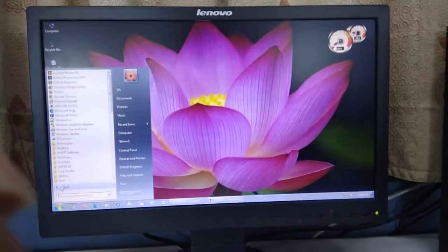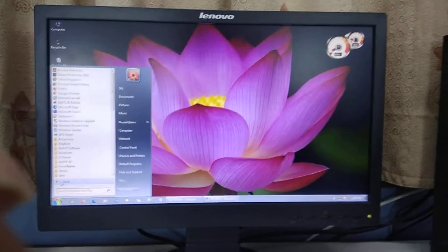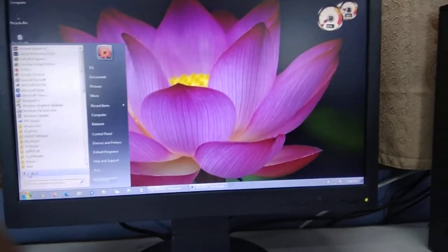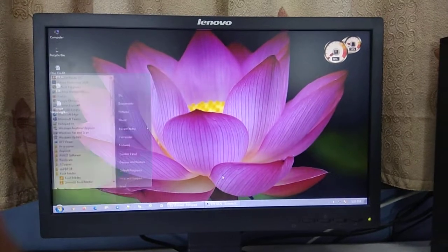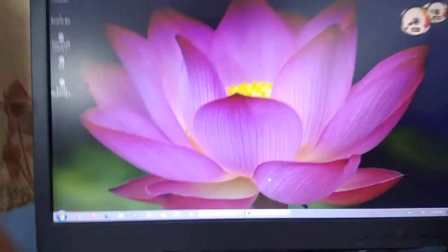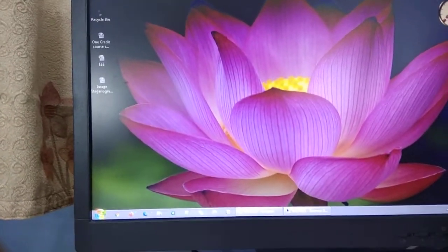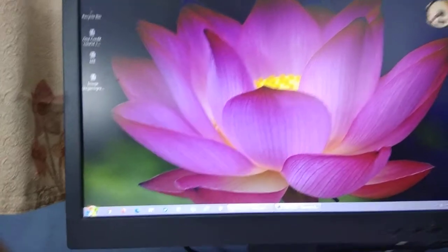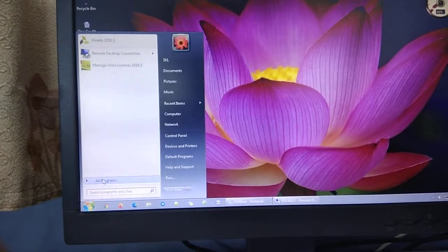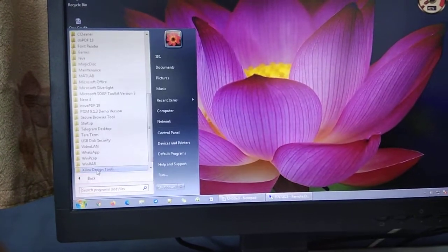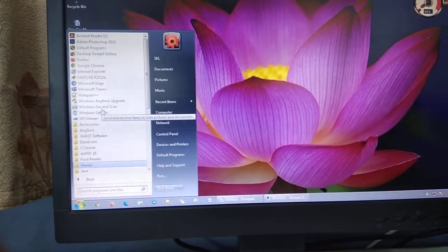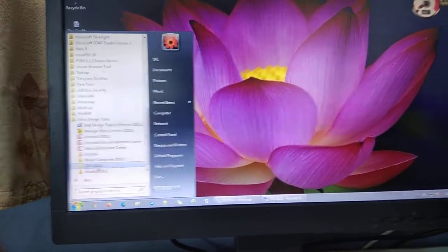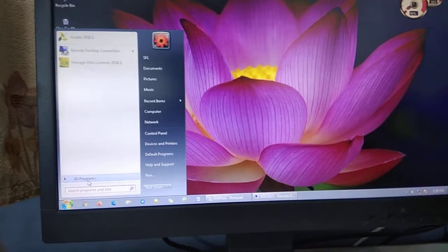Hello students, in this video we will be seeing how to simulate a VHDL or Verilog program by using Vivado software. So for that, you can open the software from the start menu. After the installation we will have the Xilinx Design Tools folder. If you click start menu, all programs, at the last you have Xilinx Design Tools. Here also it will be there.